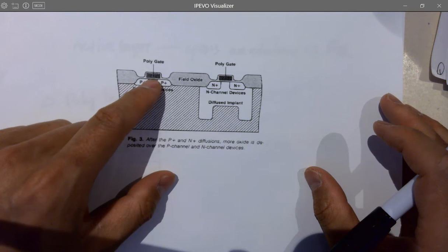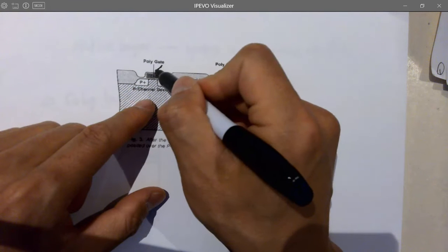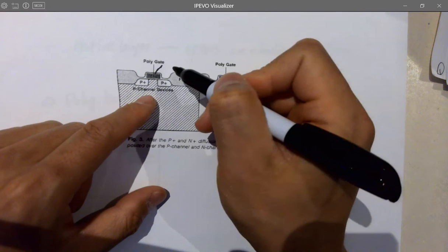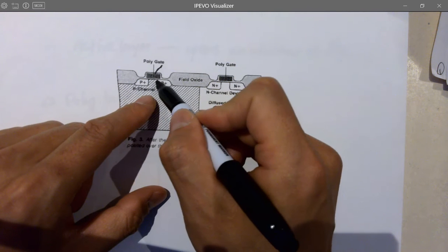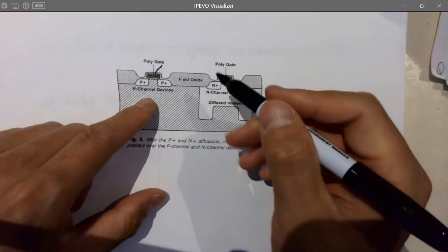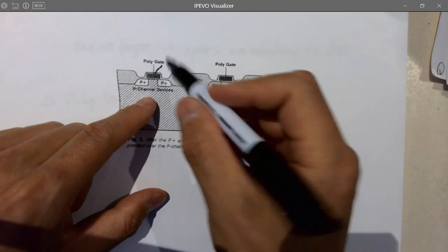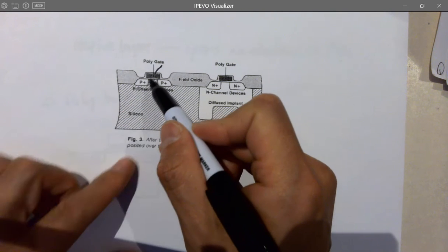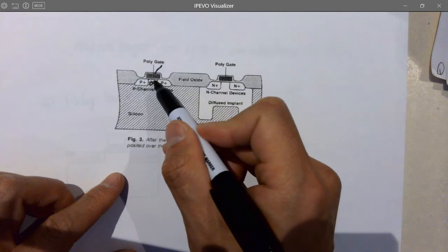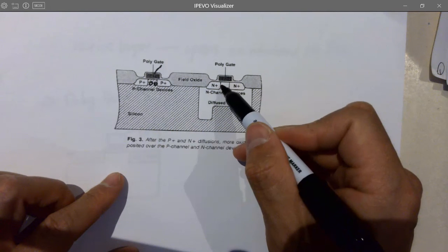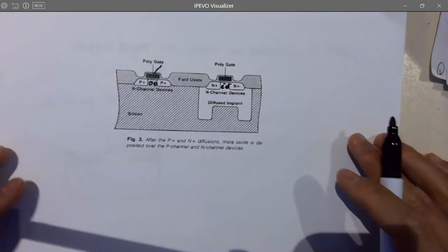And so what's the field effect? It's an electric field, right? It's the voltage applied to the gate, and then it forms the electric field instead of directly dumping current into it. So electric field, for example, for the PMOS, it attracts holes. For NMOS, it attracts electrons. So that's a field effect, right?